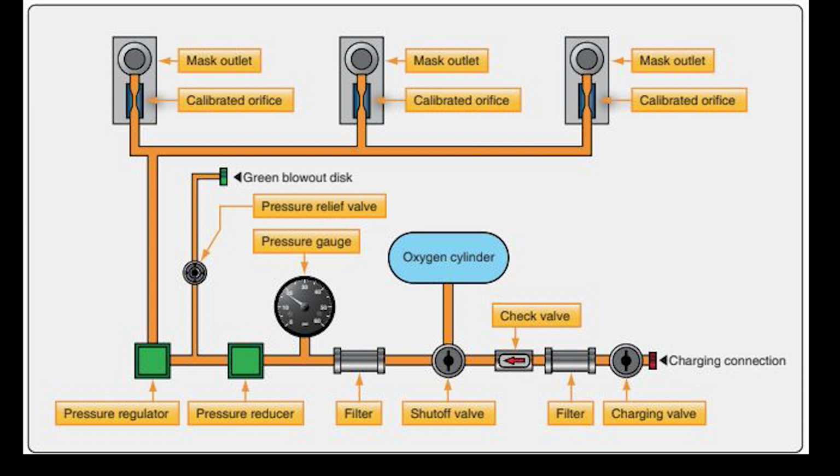The thing that I want you to pay the most attention to is the charging valve, because that's what you're going to end up doing. You're going to end up hooking up and servicing the oxygen system on a regular basis. This could be every week or so you're going to go check the oxygen level, or after so many flight hours, or simply during preflight the pilot knows, hey, look, our oxygen is getting a little low. We need to get it serviced. Not a big deal. Take the oxygen tank out there, hook it up, charge it, raise the level up, close the valve, and off you go. No big deal. But that's what that charging connection is for.